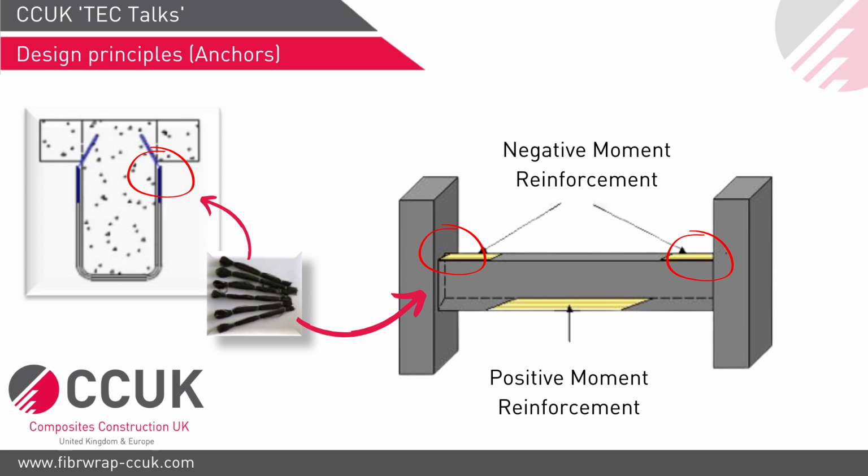Then if we look at the use of bigger anchors, it's not here. There are specially designed anchors as well, called super anchors, which we use to transfer forces from one side to another. The anchor next to the left-hand image is a nominal anchor, a standard size of 150 millimeter. But if we have a bigger column size, we can use a longer anchor, called a super anchor, which is specially designed for a particular force.